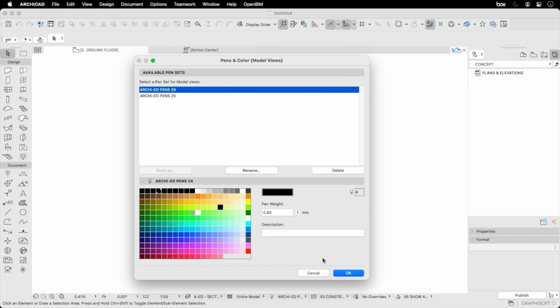Therefore, I don't want to use color to represent thickness. That doesn't make sense. I want color to represent color. If I want the drawing ultimately when I print it to be black, I'm going to use a black pen. If I want the lines or the fills to be colored, I want them to show as they will print. That was the premise behind 24, and that's why we see there's such a range of colors, and the first 10 are pen thicknesses that will all be black.